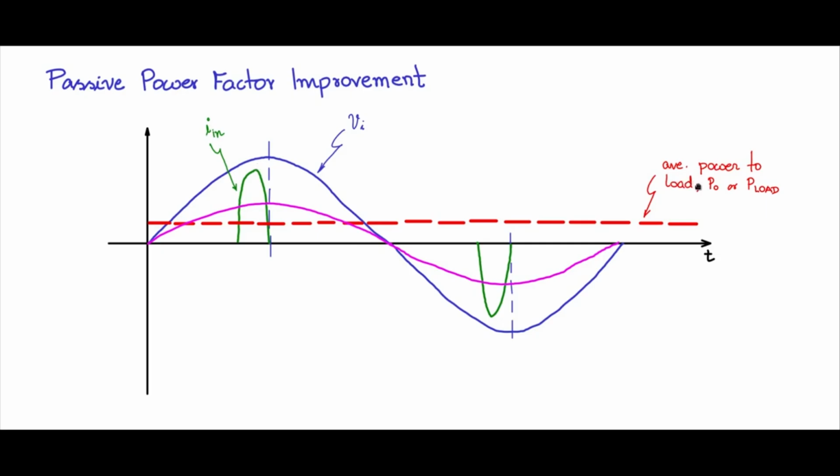That is because for the same load, if I had a resistive load, the current is conducting for the whole cycle because the current has to be in phase with the voltage and have the same wave shape. And Vm Im by 2 is the power that is delivered to the load. Therefore, Im is fixed by that, and you will see that the Im is much lower than what you would get for the case of the rectifier capacitor filter for this particular P0.